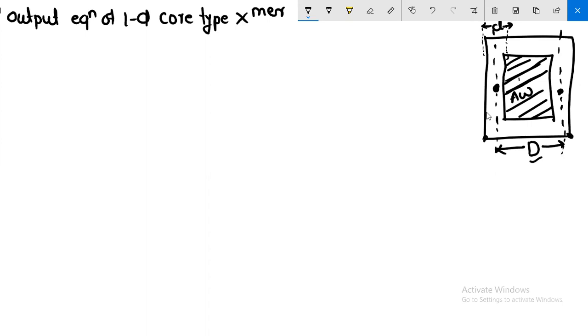Now what is this small d? That small d stands for the diameter of a circumscribing circle. So what is the meaning of circumscribing circle? See, although our core is actually from here to this particular point, what we have done is we have considered somewhat of an extra part. See, I have not drawn the dotted line fully on that line, I have shown it slightly ahead. Why? Circumscribing circle means whatever the effect of magnetic flux is, that is applicable up to that point.